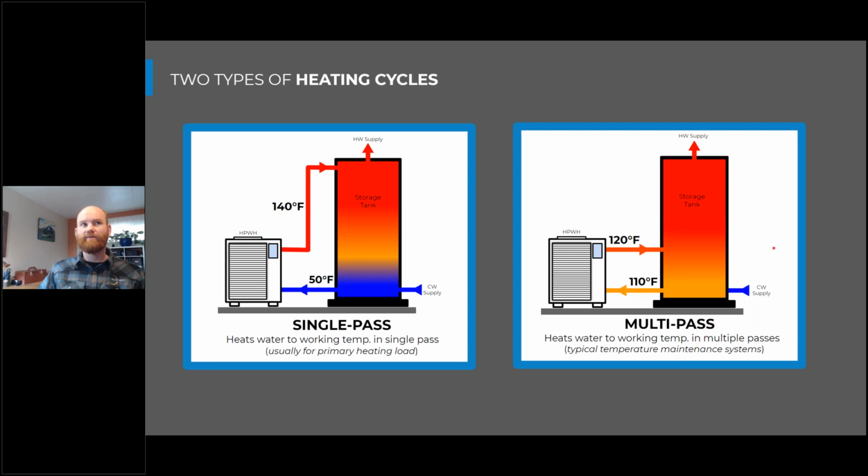So that's one really important aspect of heat pump water heaters to understand, is not only what technology and refrigerant is being used in that heat pump water heater product, but also what the heating cycle is designed as, whether the manufacturer allows you to specify a single pass or a multi-pass heat pump water heater, or if their product is only suited for a single pass operation.